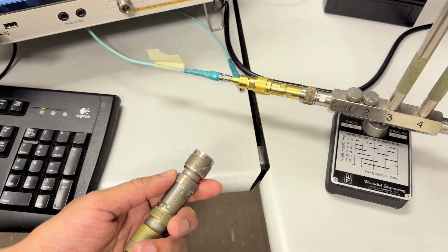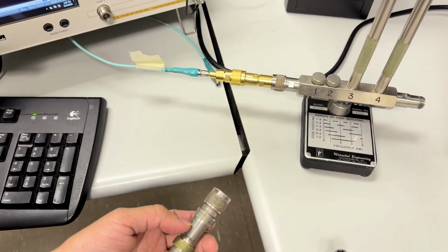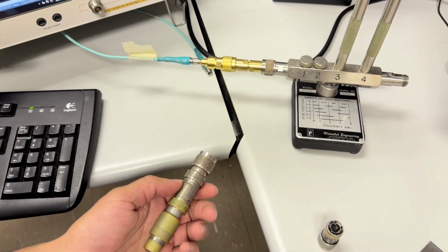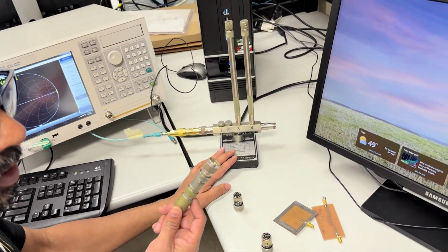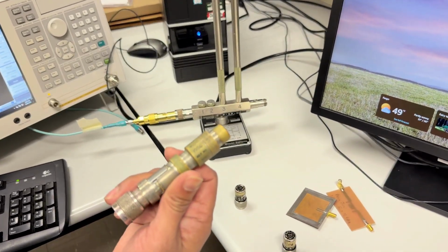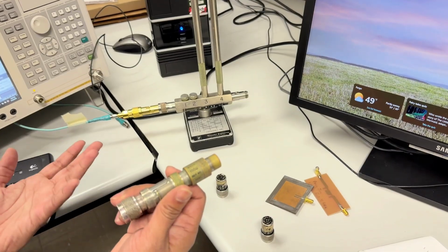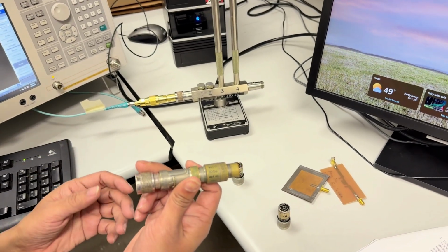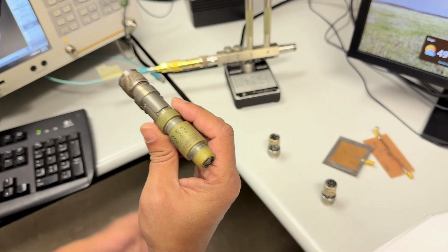Okay, so now we are moving to part B. We are done with the 50 ohm load, and we are moving to part B. This is a very interesting part because this time we are not going to use any 50 ohm load. Rather, we are going to use a 100 ohm load. That means definitely this is not a match situation, because the characteristic impedance of any load or antenna is 50 ohm. So that means you have to match it with the antenna.